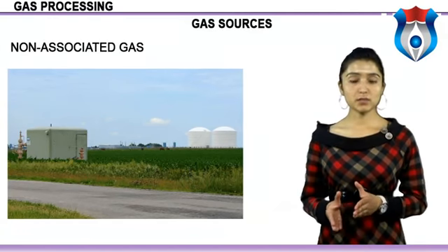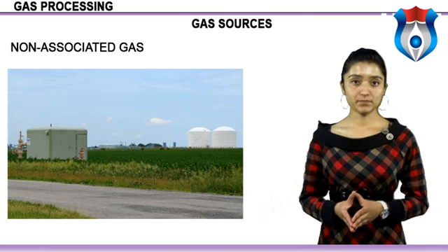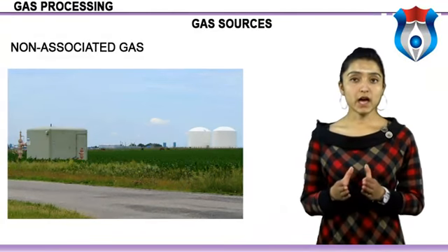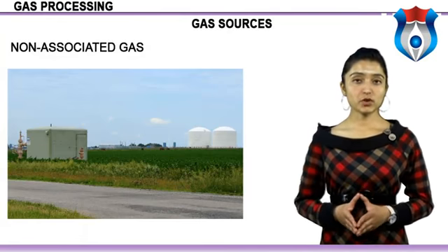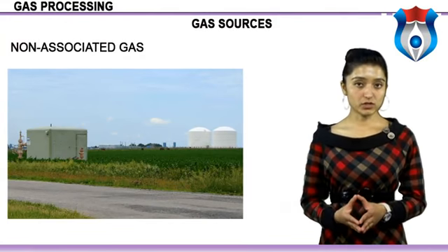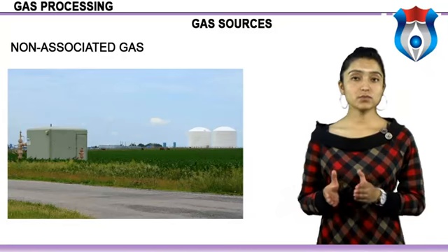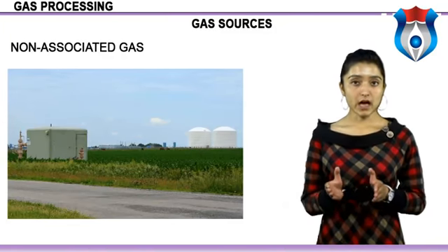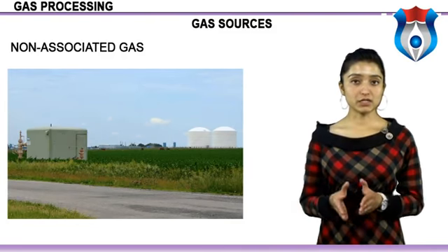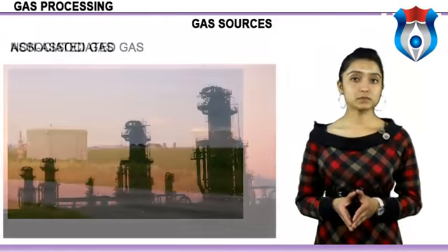The gas flows up the well under its own energy, through the wellhead control valves and along the flow line to the treatment plant. Treatment requires the temperature of the gas to be reduced to a point dependent upon the pressure in the pipeline, so that all liquids that would exist at pipeline temperature and pressure condense and are removed.